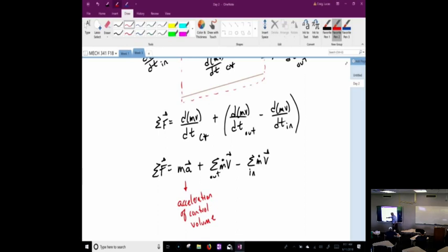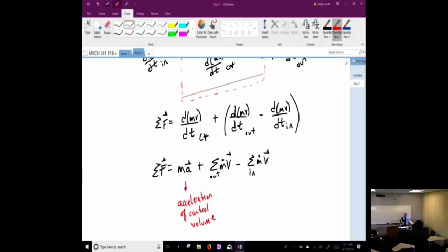So if you look, these are all the forces that we had in the spigot, and we labeled what's coming in and going out. Then we can write the flow rate coming in times that velocity in that direction. Now, let me show you why it's out minus in. So let's look at the little dragster car.